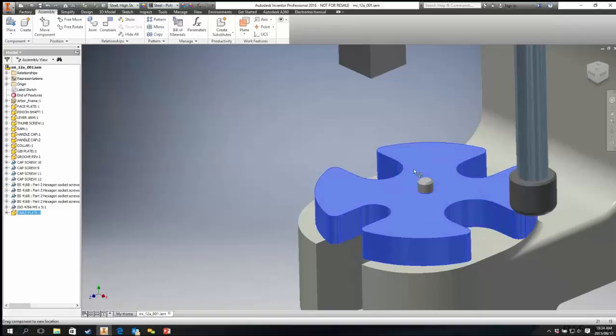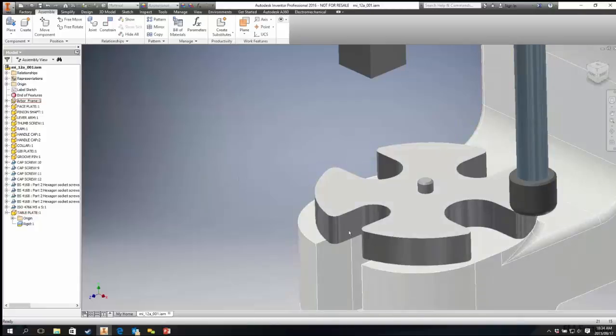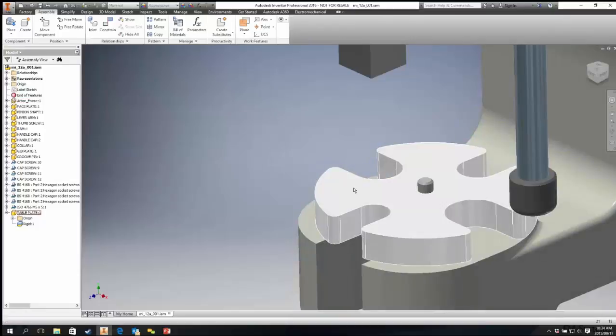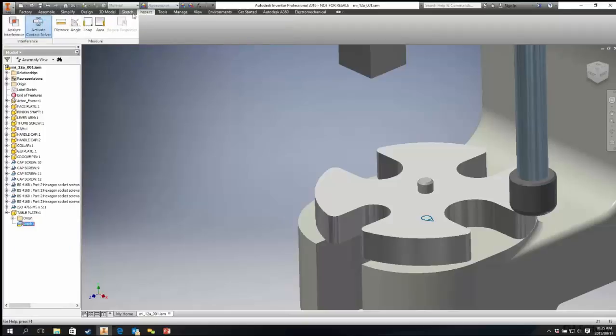So with this type of joint, immediately with one connection, I've set up the connection of how I want this to exist. Meaning I didn't have to go and make two faces and then look for a center plane to align with this one or use an angle constraint. I could have basically just done this with one joint, which is now called rigid. And what's nice about this, you can always toggle between it if you realize that there should have been a different degree of freedom. Let's quickly put that on so you can get to see what I mean by the different degrees of freedom. So I'm just going to go and enable over here.